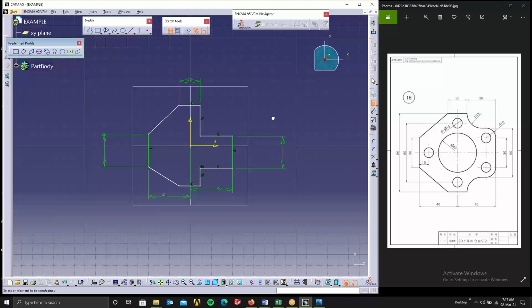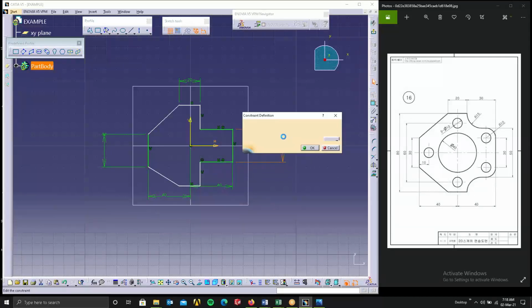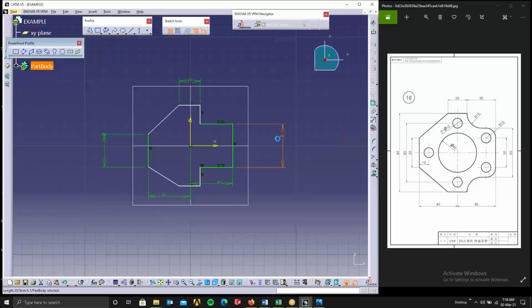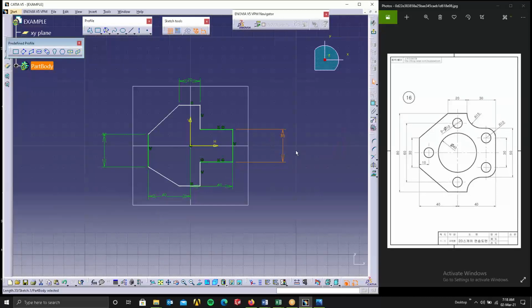from here. Okay. Then our constraints also, I'll select this, and I'll select the horizontal. Okay, just observe this side and the horizontal. Constraints, I'm going to give symmetry. If I give symmetry, no matter what I change here, see, if I give this 40, here also automatically it'll change. So that's why I give symmetry command. So I'll give 30, enter.